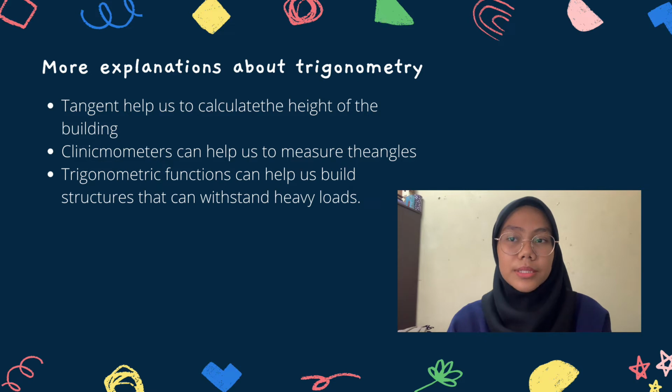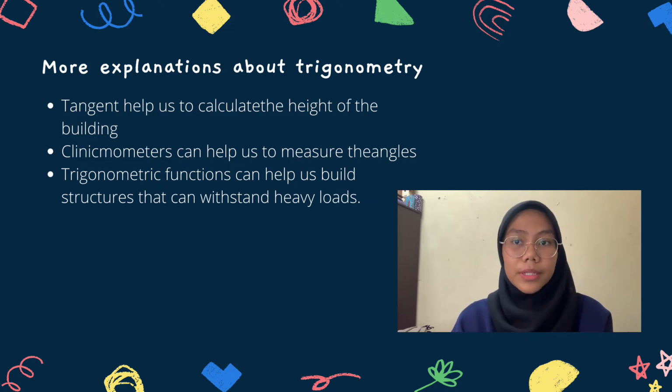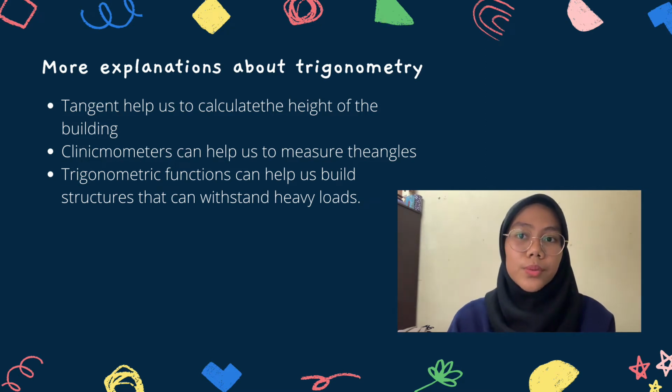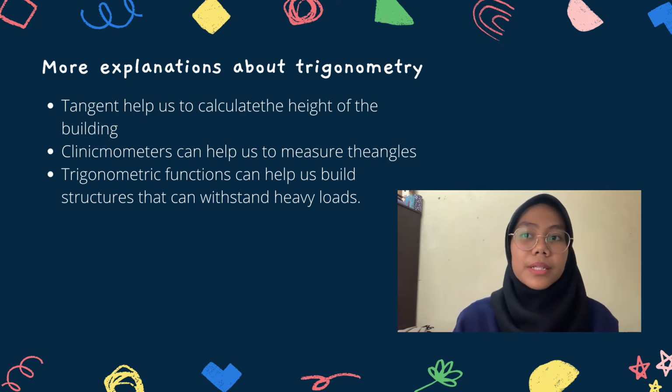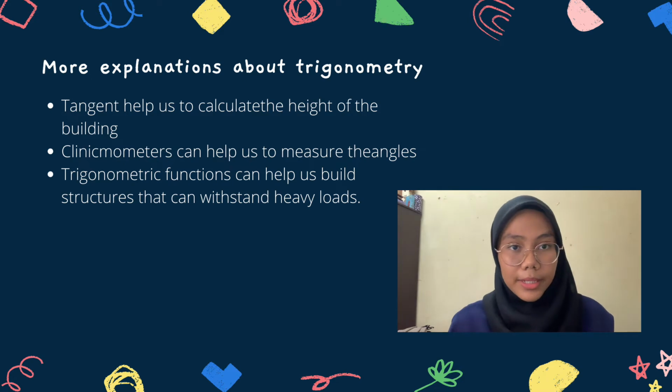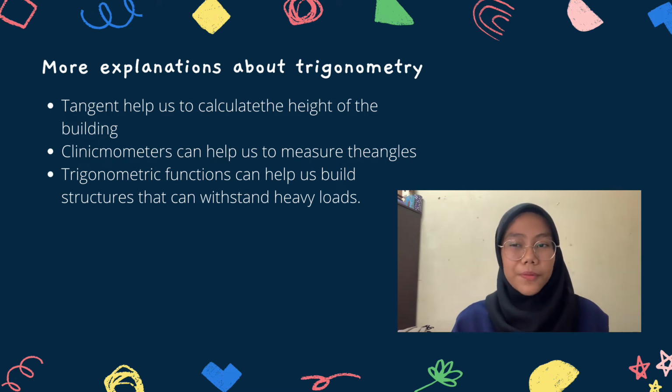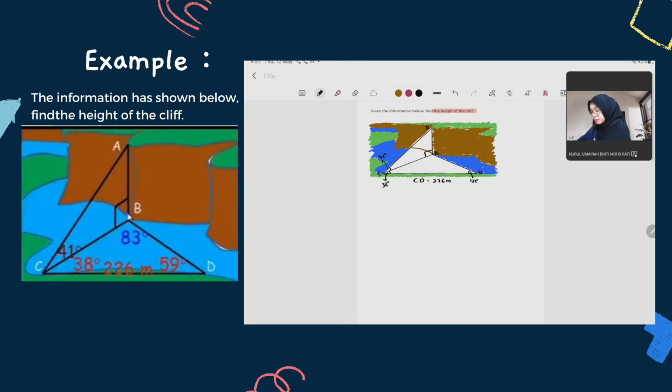The angle of trusses, which provide support for the roof, and the length of the rafter are decided using trigonometry. If you have a triangular roof and the length of the rafter and the length of the roof horizontally are known, you can apply the cosine function to calculate the angle at which the trusses should be cut for the maximum amount of support.